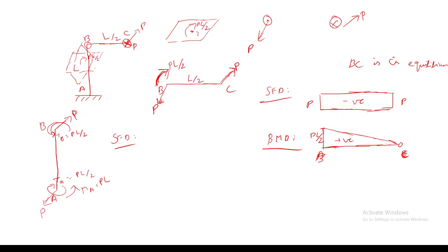So this is point B, and this is the member BC, and point B is connected to this member A. For BC it is a bending couple, since the loading is perpendicular to this cross section, whereas for member AB it will be a twisting moment.